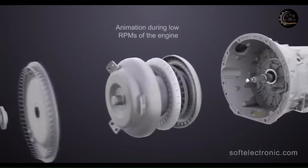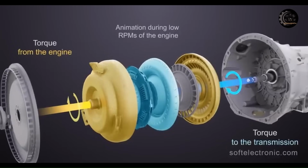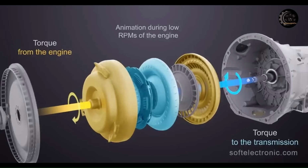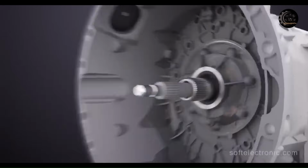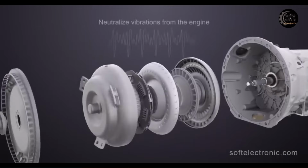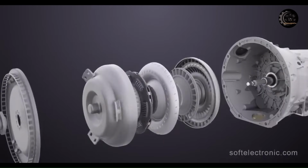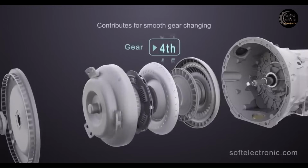To improve fuel efficiency and reduce heat generation, many modern torque converters are equipped with a lockup clutch. The lockup clutch mechanically connects the impeller and turbine once the vehicle reaches a certain speed, bypassing the fluid coupling effect and reducing slippage. This creates a direct mechanical connection between the engine and transmission, improving efficiency during cruising conditions.